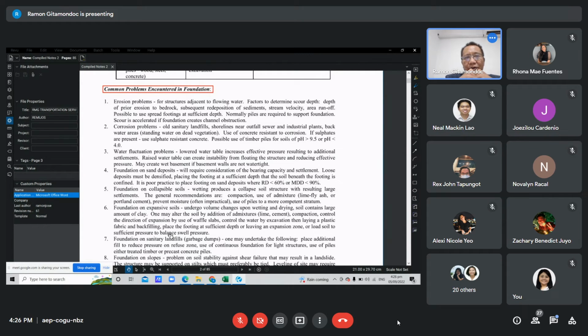There is water in their basement due to leaks. So the important thing is the design of the basement. If it lacks reinforcement, when it is subject to hydrostatic uplift, the concrete will crack. We have encountered that in some areas here.